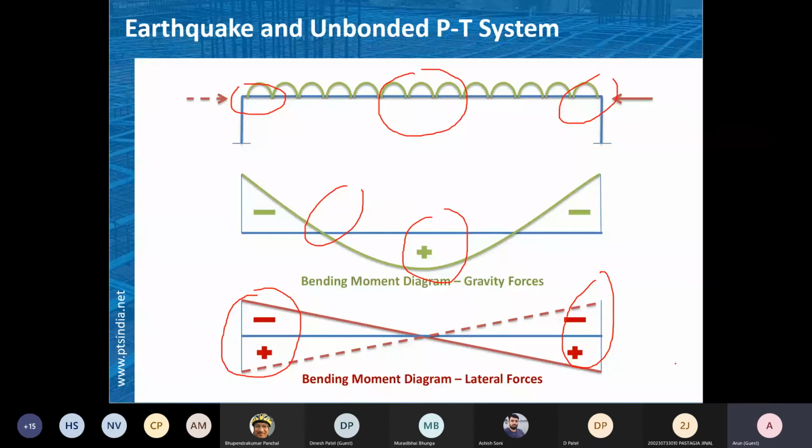Now, if we see what the permanent forces in our system are, one of them is the self-weight of the structure. If you compare the self-weight of the structure with the imposed loads, the self-weight itself is more than 60%, 70% of total load, right? And when we are discussing large spans, this goes even higher, because large spans require more concrete and ultimately more self-weight.